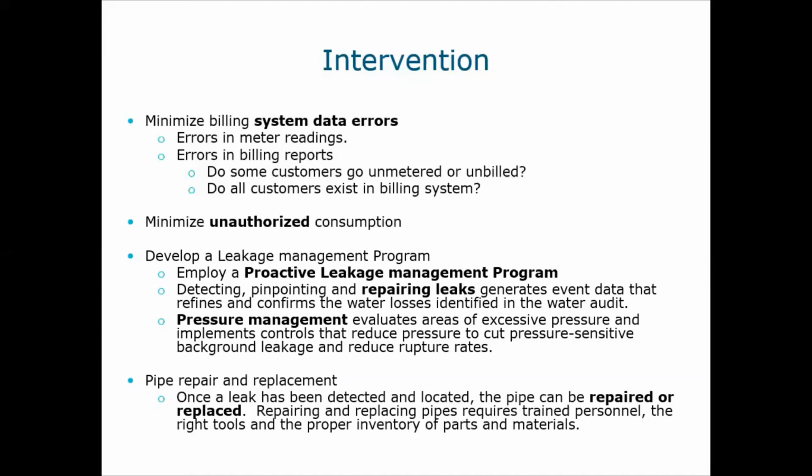And then again, we've got to look at our pipe repair and replacement. If we're finding 35 breaks on a 1,000-foot stretch of old cast iron, you may want to take a look at replacing that pipe versus repairing.